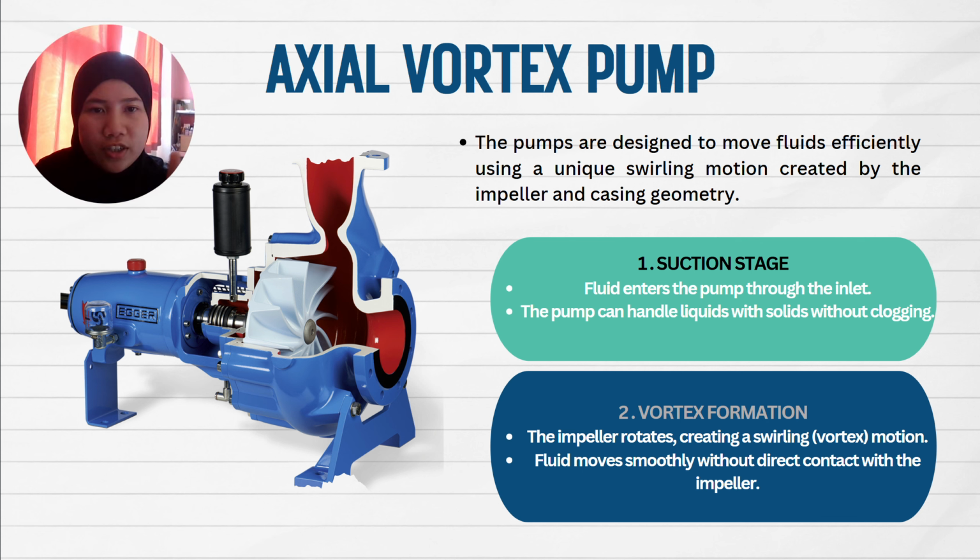The first stage is the suction stage, in which fluid enters the pump through the inlet. The pump can handle liquids with solids without clogging. And the second one is vortex formation, in which the impeller rotates and creates a swirling motion, and then the fluid will move smoothly without direct contact with the impeller.